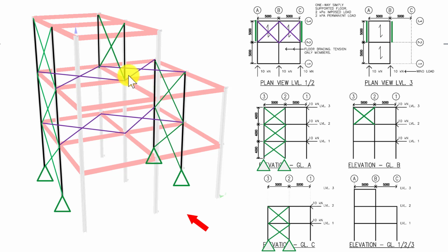And that floor bracing could be a concrete floor, it could be steel decking, or it could actually be physical bracing installed. Normally it's not as neat as I've shown you in real life because there's beams in the way, so often you'd have funny bracing in between those beams, so it looks less elegant but then fits in with the floor beam arrangement. Now once I have this, the entire structure is stable. I can carry loads from every node laterally or vertically down to those foundations.